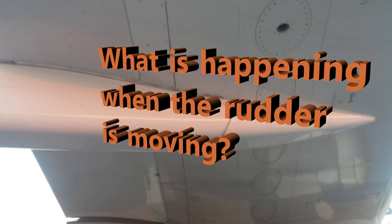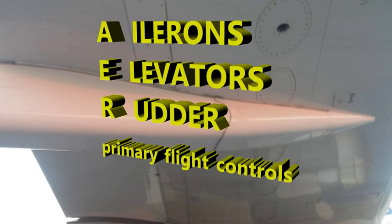What it's doing when the rudder is moving, it's changing the airflow, as many of these control devices are doing. It's what all of them are doing, actually. But depending on where they're positioned or located on the plane, it's going to have a different effect. And here it's redirecting the air passing the fuselage. Okay, those are your basics. Just think of AER. That's your ailerons, your elevators, and your rudder. AER comprise your primary flight controls.